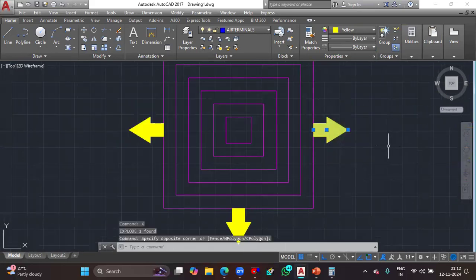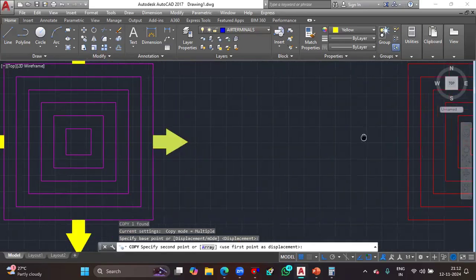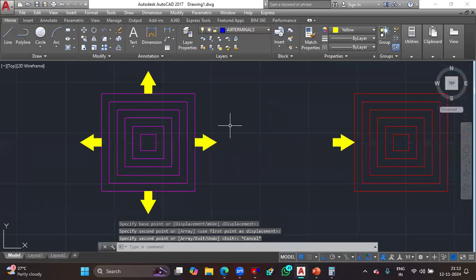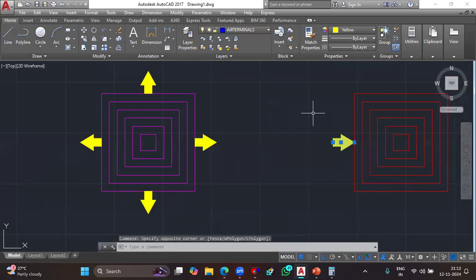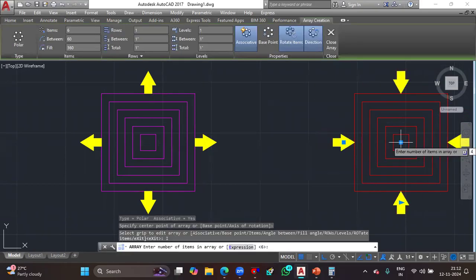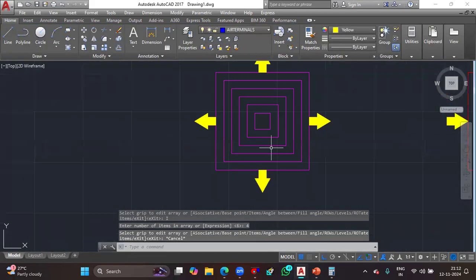After that, select this option, copy this one, pick this arrowhead and directly paste onto the other end. That's why I linearly pasted it. You can see the importance of copy-pasting in this method. Once it's done, again do the same thing, guys: polar array. Select the midpoint, then items, enter, 4 number of items. That's it. Now your supply and return diffusers are ready.